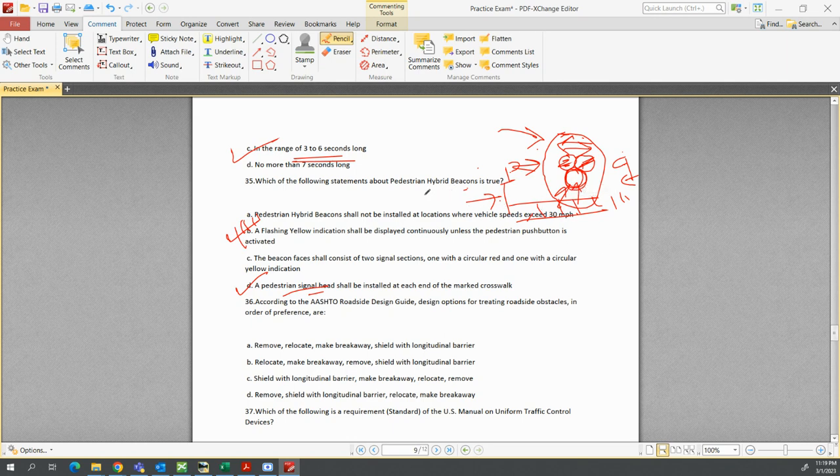But let's say somebody came here and pushed the pedestrian button on this pole. At that time, the yellow one starts to flash yellow. After that, it turns to a solid yellow, and then when the pedestrian signal gives a clear signal to cross the crosswalk, these two traffic signal heads above start to flash red. So this is how it works basically.